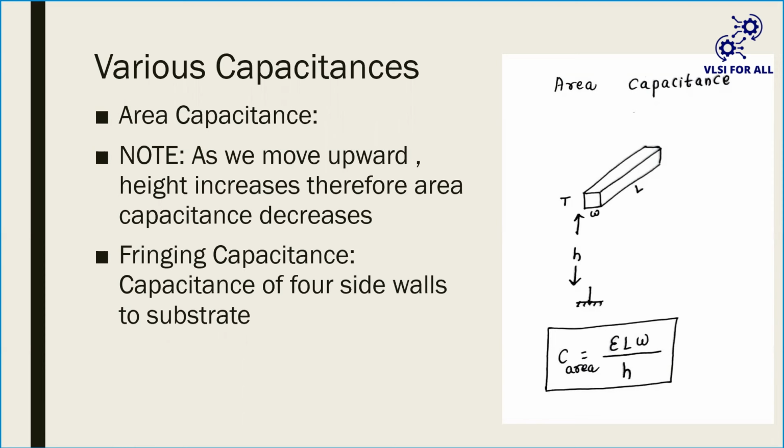But when you go below micrometers, inductive effects might not be there. That is the reason everywhere we consider resistance and capacitance only, not inductance, because the size is very, very small, less than nanometers. So in such a case, you don't get any inductance, remember.